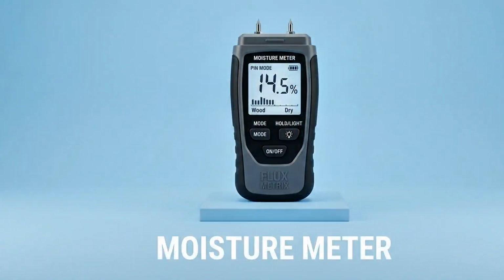A moisture meter measures the amount of moisture present in wood, concrete, drywall, and other building materials. Excess moisture can cause mold growth, wood decay, paint failure, and flooring damage. Builders use this tool before installing finishes to ensure that materials are dry enough for long-lasting performance.